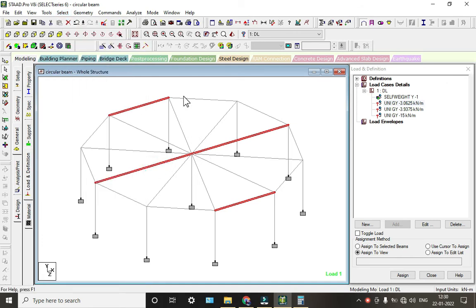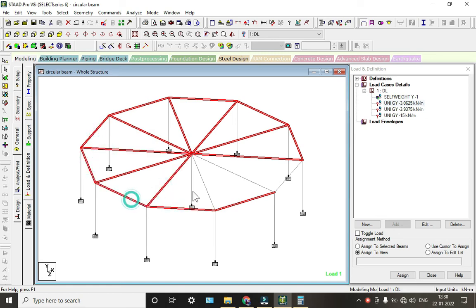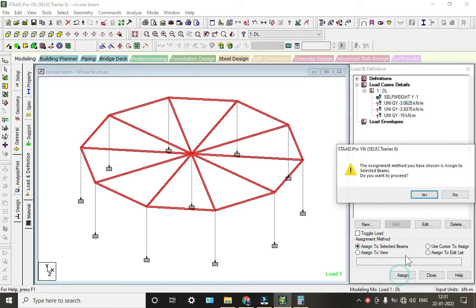Now we will design this part. Go to design, select concrete, select this IS456, and go to select parameters, deselect all of these. We will be selecting compressive strength, yield strength and shear reinforcement. Here you are going to take maximum and minimum reinforcement, click on OK.